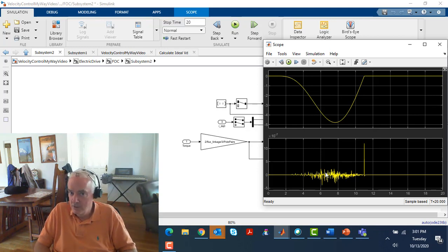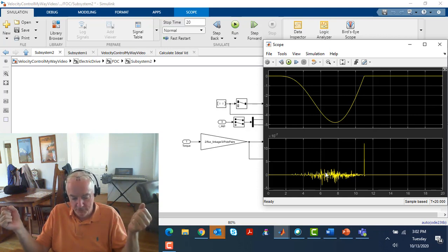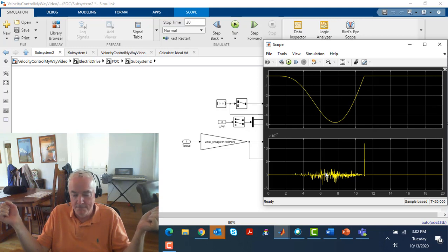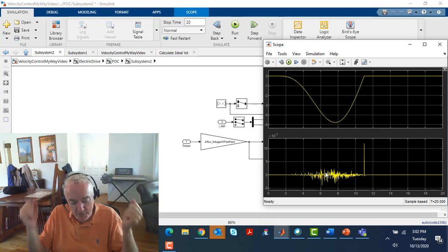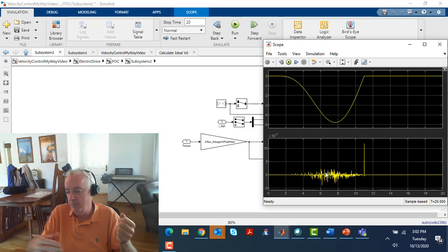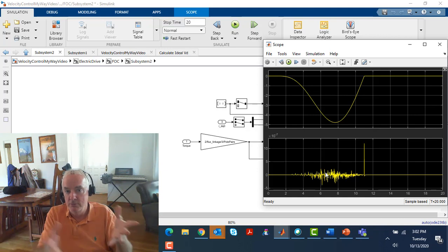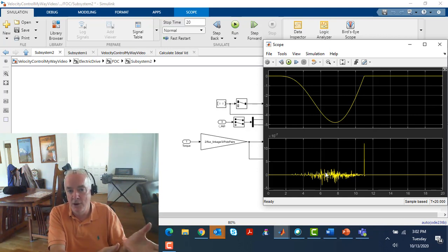Okay, but controls do a great job and they keep it vertical, right? And so what I want to really point out with regard to feed forward systems, unless it's an incredibly stable system, you always want to have feedback, right? And the premise of a feed forward control system, as we see in this example, is that we presume we know everything that's going on with the system.